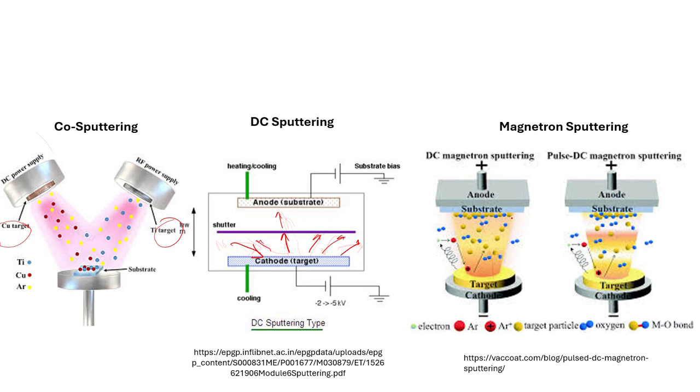But in the case of magnetron sputtering, we use a magnetic field in order to control the direction as well. So we will have more control over how the target ions are moving inside the chamber. Since we have better control, we can ensure that most of the target ions that are leaving can reach the substrate.